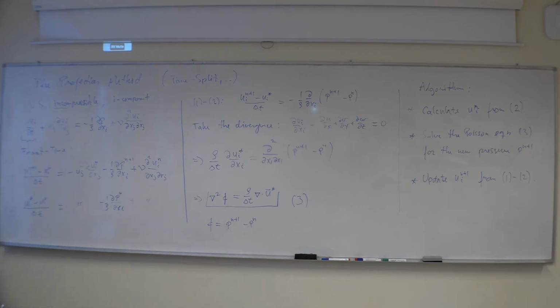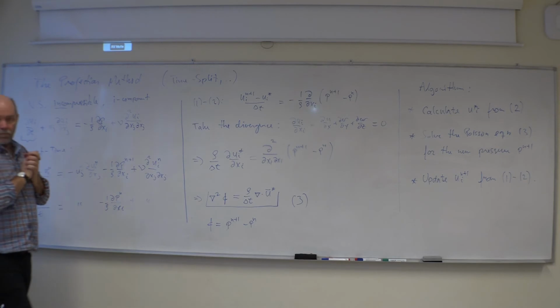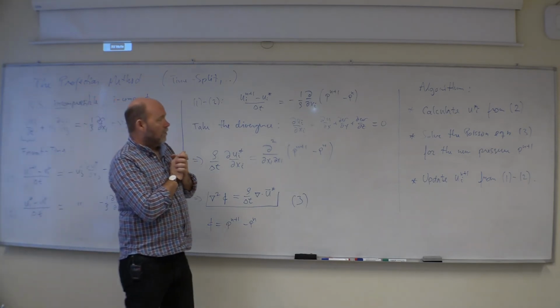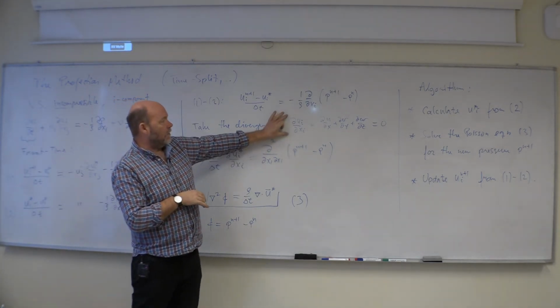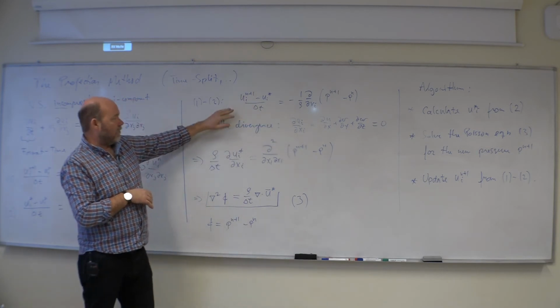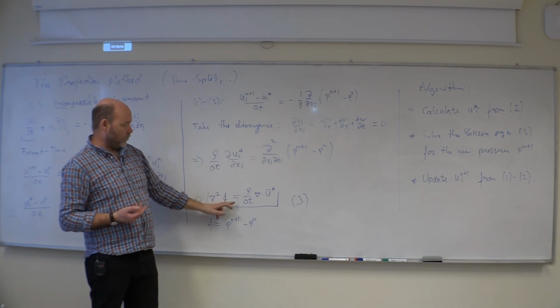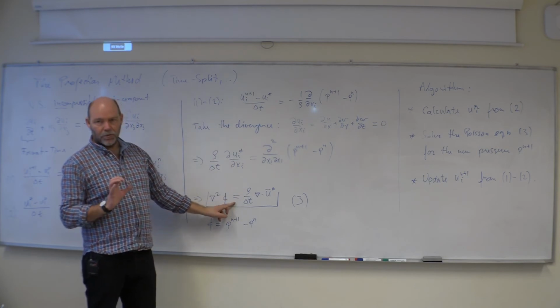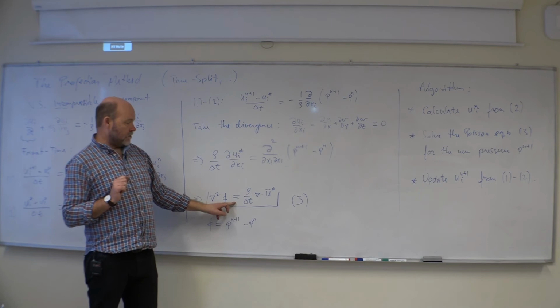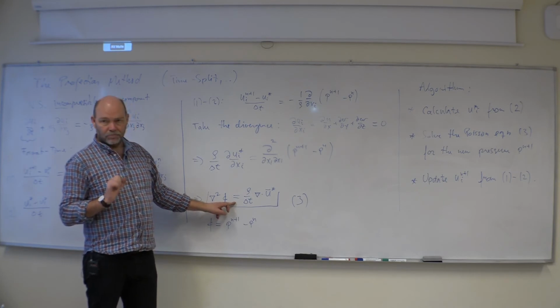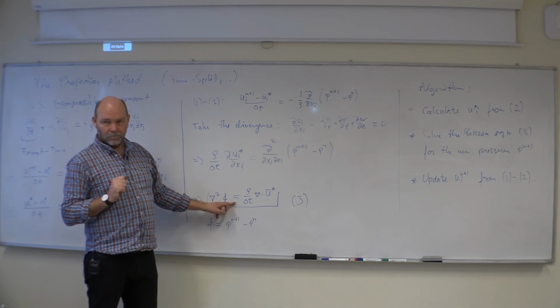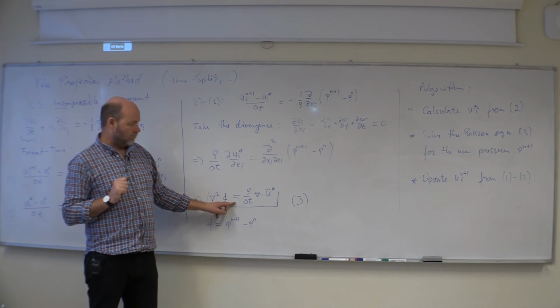Any questions to this one? So the continuity equation is kind of introduced by this divergence equal to 0, or you have to use it? No, it's given just so that this one disappears from our equation system and we are left with one simple pure Poisson equation only for the new pressure. So you still have to introduce the continuity? Yeah, you have to use the continuity.